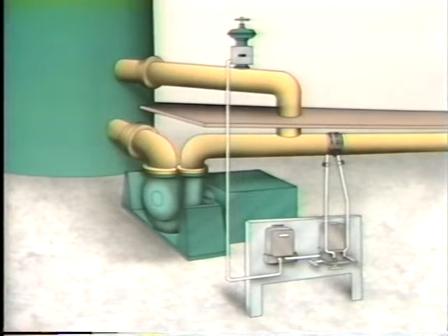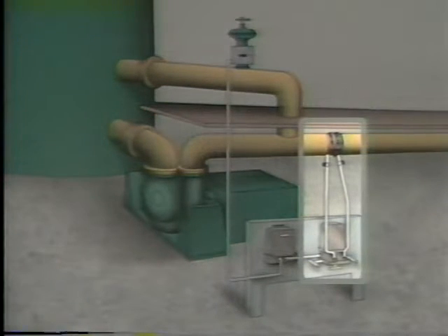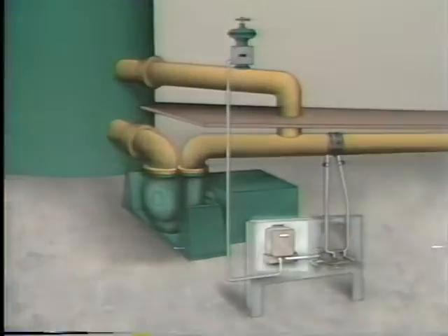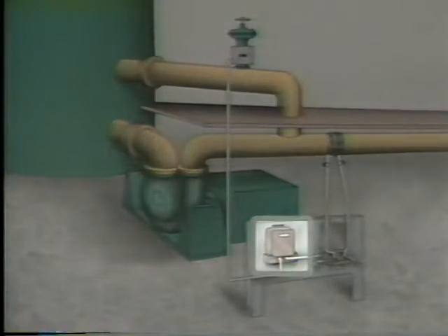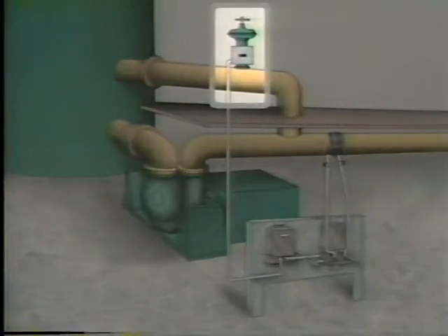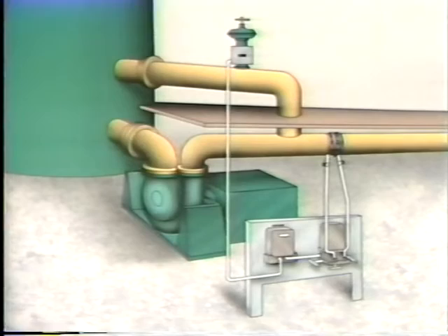As in the pressure control system, the transmitter in this system contains two of the four elements normally found in a control system: the primary element and the measuring element. Again, the controlling element is the controller, and the final control element is a positioner and actuator that operates a valve in the recirculation line. Let's see how this flow control system works.